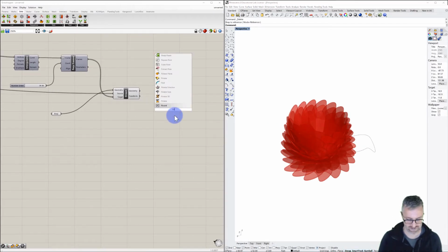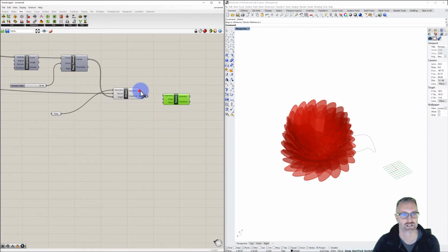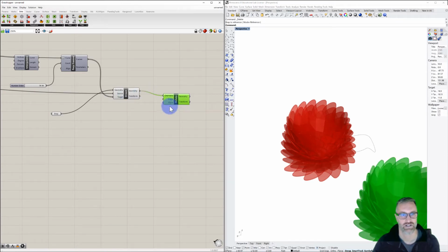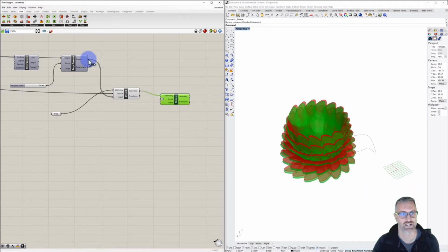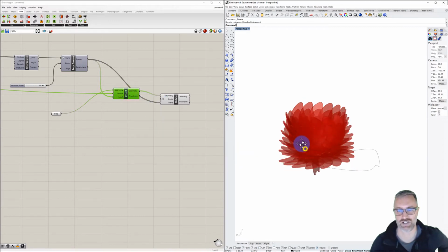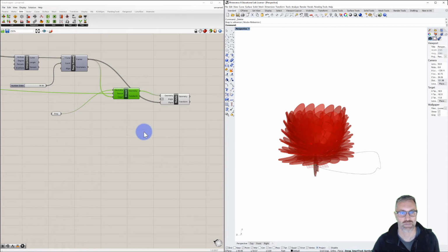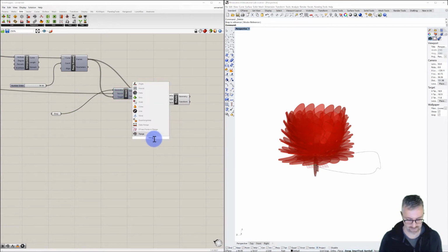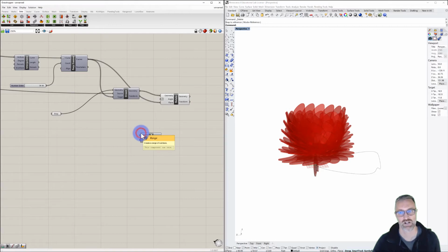Let's set a rotation, because I want to imagine all of these as more kind of facade panels. So let's rotate the oriented objects. We'll leave the angle, we'll set that to be a degree. Let's set the plane to be the frames. We can hide our oriented objects, and nothing's changed yet. But let's set a range now, because it looks like we want to go from some version of rotating something 90 degrees to not rotating it at all. And so let's set our domain.